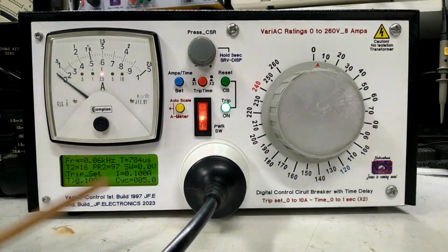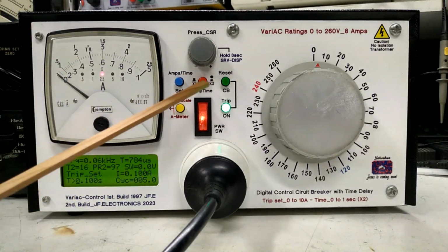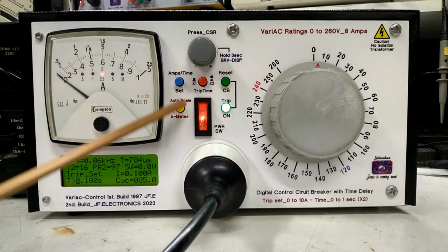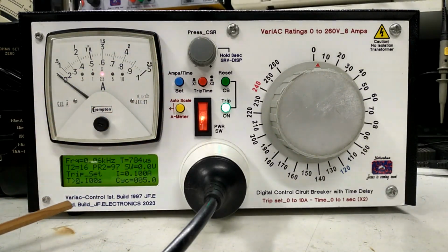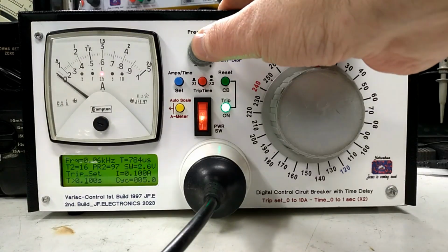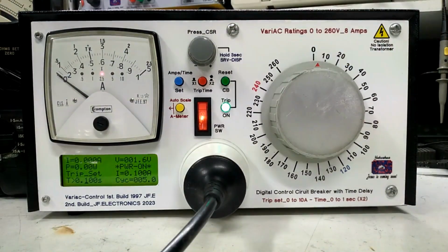So that's the internal values what the analog to digital converter is reading on the switches, because I'm only using one port, one IO input, and that reads 3 switches by having different voltages. So you hold it for 3 seconds again, and it goes back to normal.